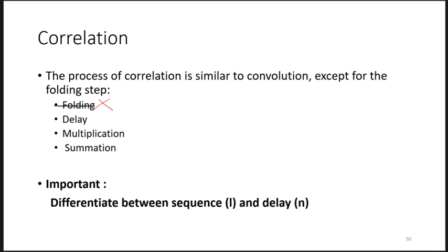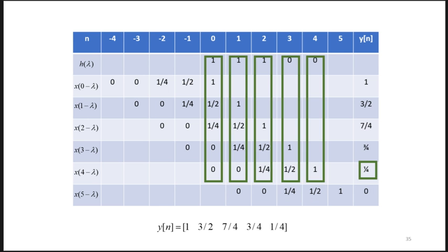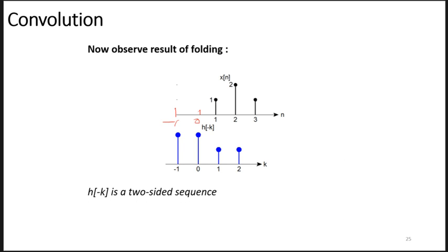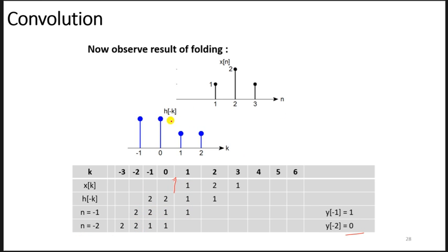Right. So I should add also, in the case when you have the two-sided sequence, if you want to be smart about it, if you see that the signal is two-sided, you shift it in advance, so that the start of the sequence lines up with the end of the sequence. Then you don't need to go left and right anymore.